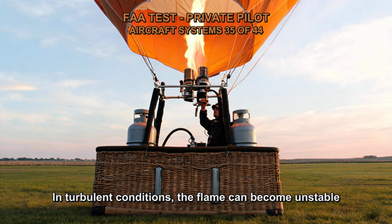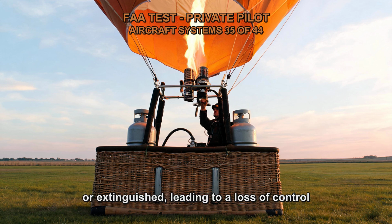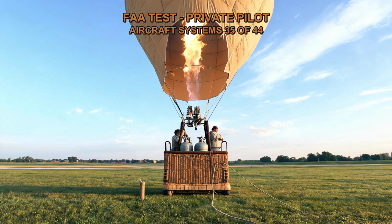In turbulent conditions, the flame can become unstable or extinguished, leading to a loss of control over the balloon's vertical movement. Therefore, it is crucial to manage the rate of descent and avoid rapid descents to ensure the pilot light remains lit and the burner assembly functions properly.